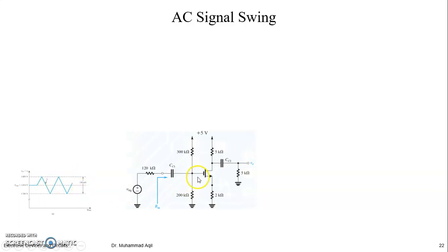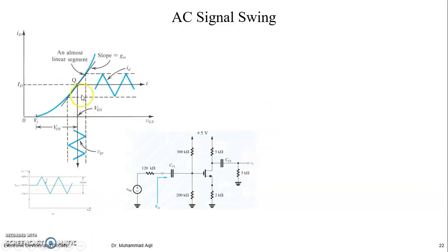And suppose we already had a DC VGS of 1.836, right? So the AC will be fluctuating about this DC. So the total is this one, right? This is the total. So what will happen? You have basically decided a VGS. This is the VGS, and VGS would be greater than VT. How much greater than VT? VOV, right? Fine with the graphical representation.